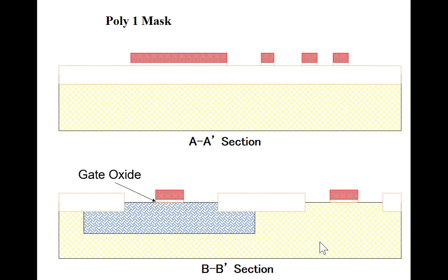So that's called the gate oxide. That's a real thin layer of oxide. That's a critical processing step. If you go back and look at the process flow, before we put that down, we first stripped oxide, etched it away, so we have silicon. Then we put the thin layer, it's going to be our gate oxide on, and then cover it with poly very quickly. Make sense? That's one of the most critical steps in this process. So here's our gate oxide under here and under here.